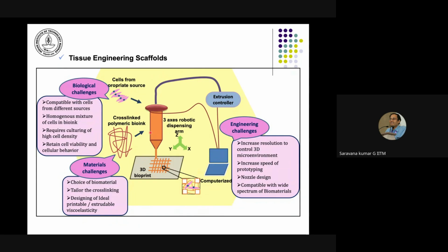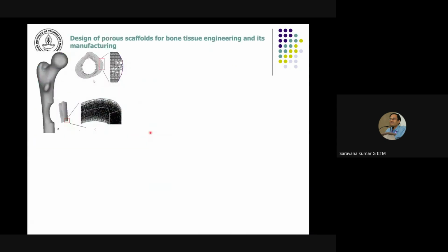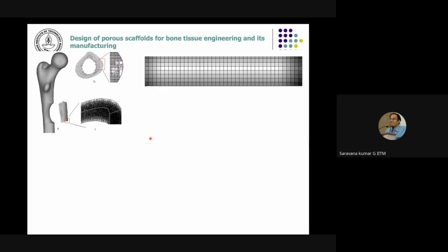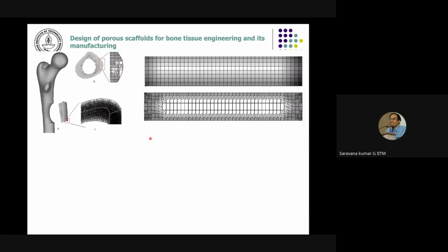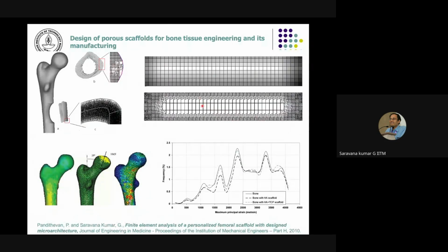In the interest of time, because I want to give some time for discussion, some tissue engineering work, particularly in bone tissue engineering: we have developed design methods to represent porous objects, because we can change the pore density and network. In fact, we have a design methodology which is a volumetric representation of the bone density, which can be translated as tool paths to deposit the material, and thereby we can develop a spatially varying density. This is in fact a US patented methodology.